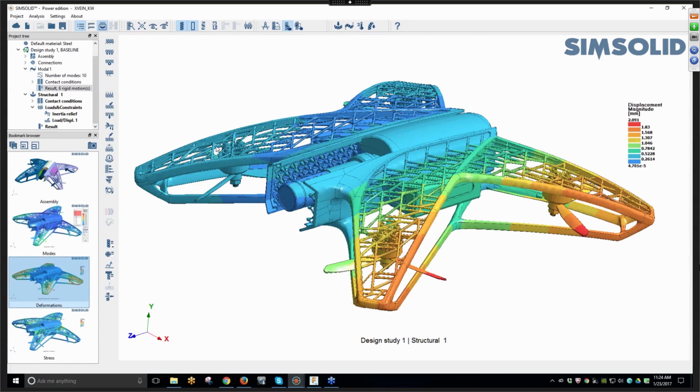So we have inertial relief. I turned on inertial relief, and then I just put one set of loads that was 100 newtons vertical, evenly divided between the 4 engine mounts, so 25 newtons upward on each of the engine mount points, and I said solve. And that took about 3.5 minutes to solve. So, not as quick as that other thing. It's very complex geometry here, many surfaces.